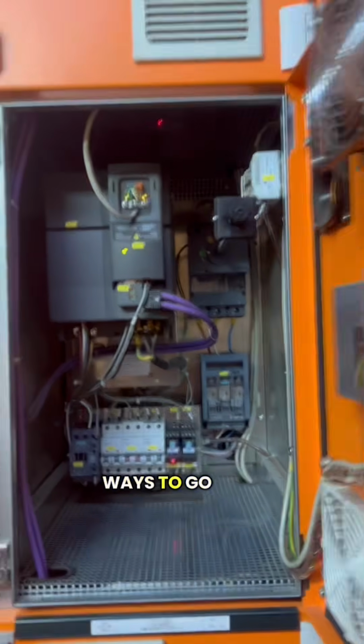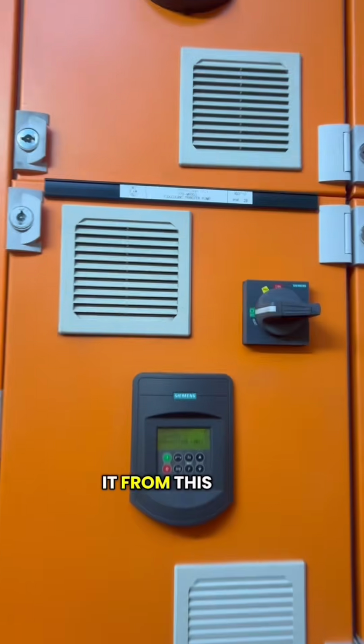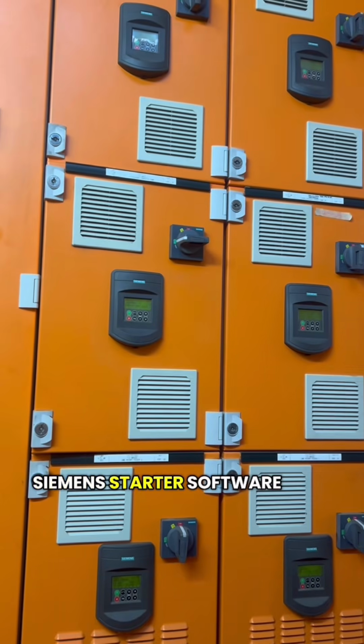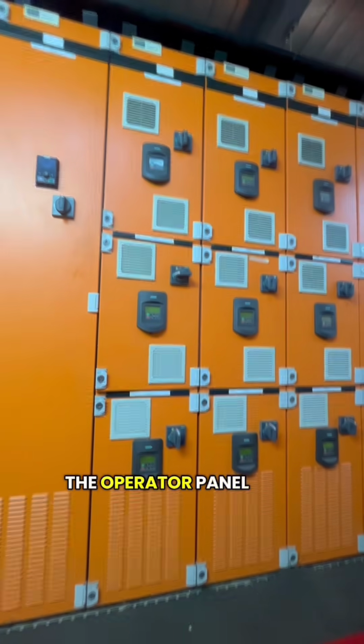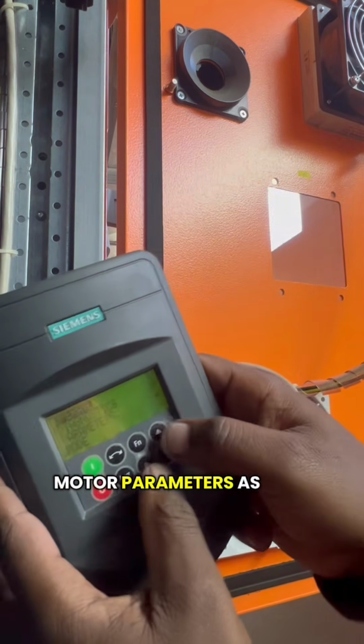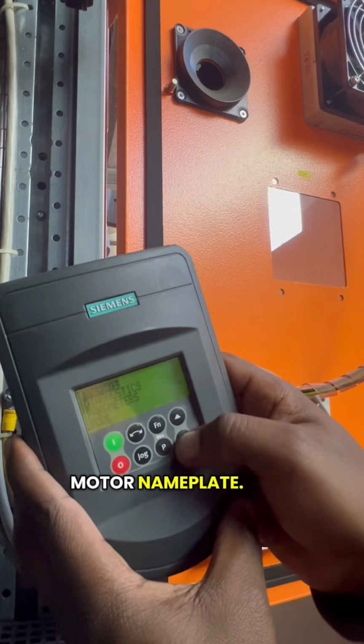There are two ways to go about doing this. You can do it from this operator panel, but you can also use the Siemens Starter software. Let's start with the operator panel. So you start by inserting the motor parameters as stated in the motor nameplate.